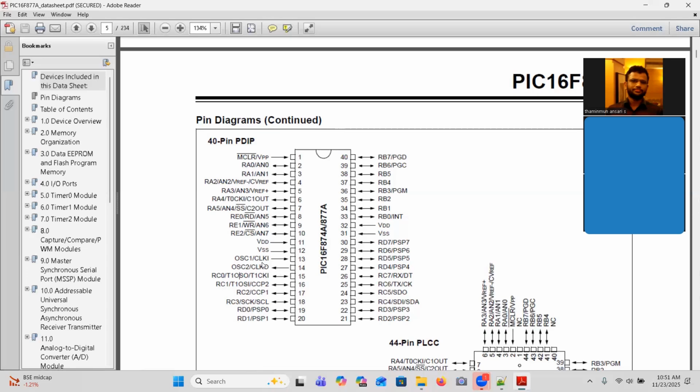When they give some clock in, they also say take some clock out. These clock outs can be used as a reference operating clock for some other electronic module. If another chip, such as a codec or an analog to digital converter, requires a clock, they can supply the clock from here. Got it now? Yes, sir.